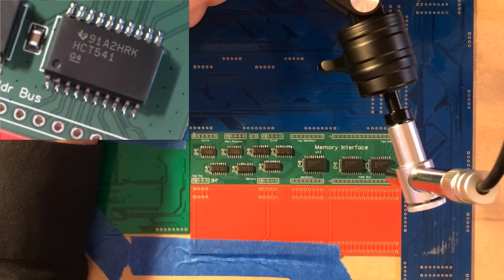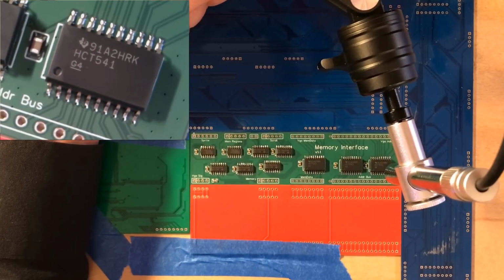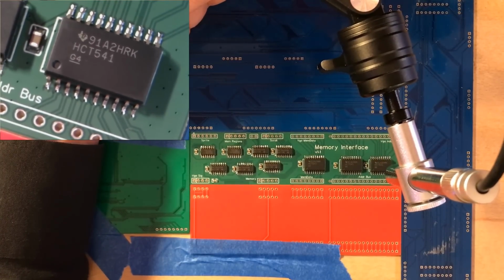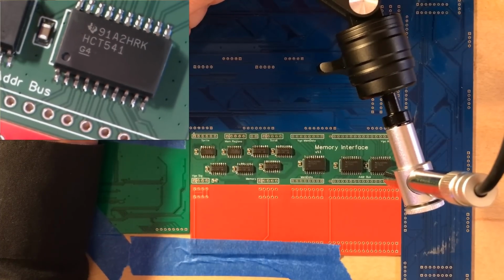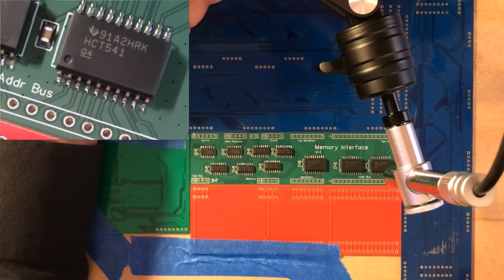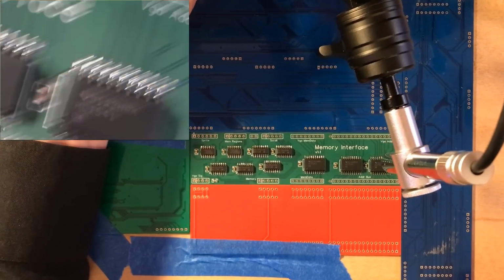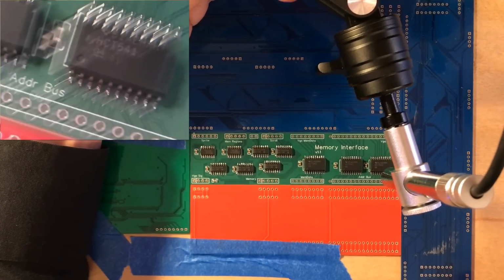Yeah, lots of joints here, particularly towards the bottom, look like they are a little bit suspect on the reflow. I think I'm going to touch up a lot of these just because the odds of one of them not being wrong. Most of them are probably fine, but I think it's very likely that there's a problem on one. So on this chip, those top ones look fine. These bottom ones look off.